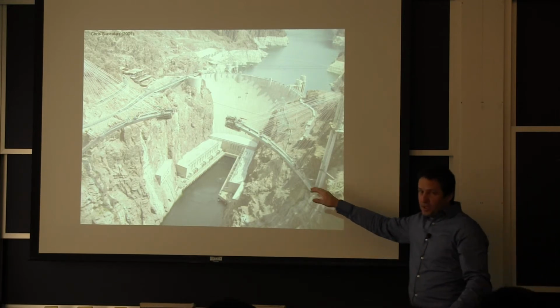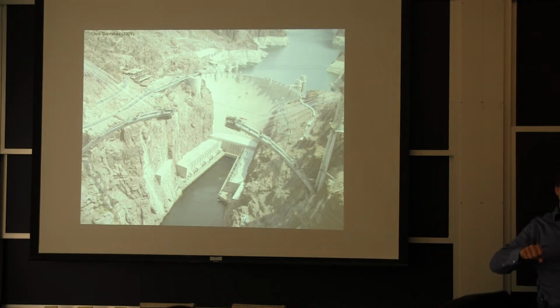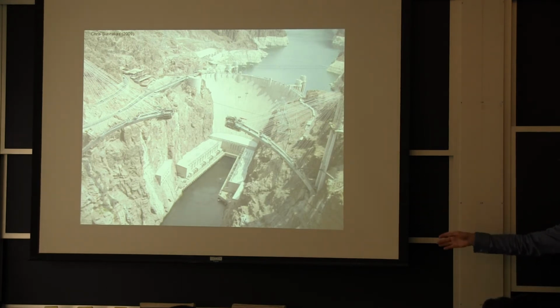For this project, each of these 50-ton segments, was it post-tension or pre-stress? I can't remember, but they had the concrete fabricator build a plant next to the project to make each segment as opposed to trucking it. So when we talk about the cost of material being really low, you bring the raw material, and they were building it segment by segment. The idea is to use the steel in tension and make sure that most of the concrete is in compression.